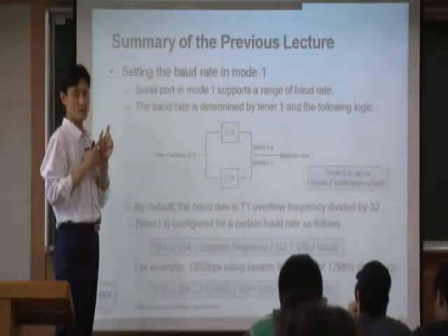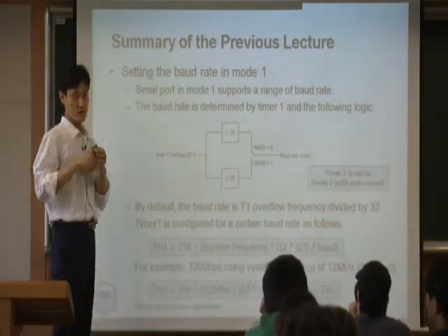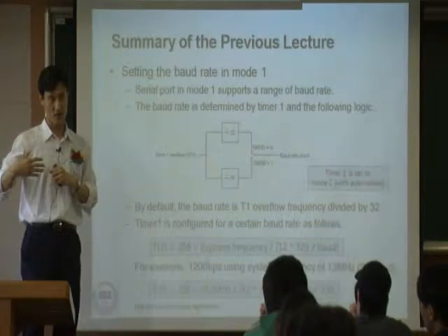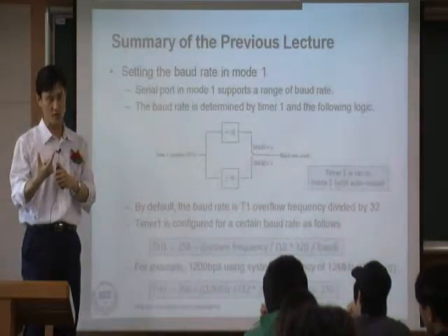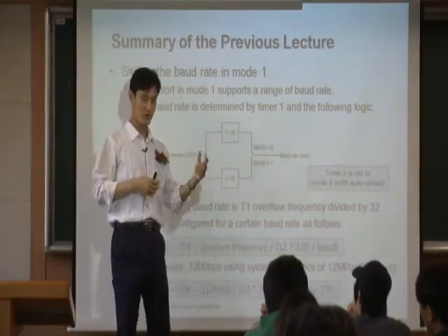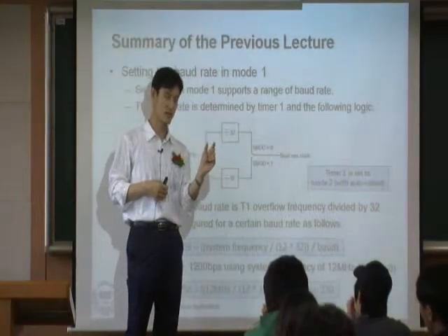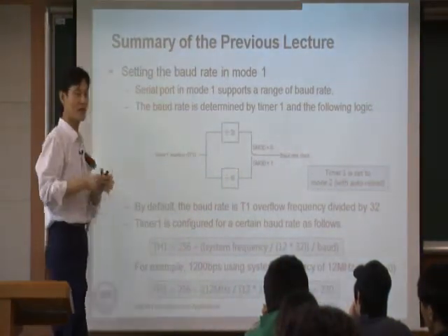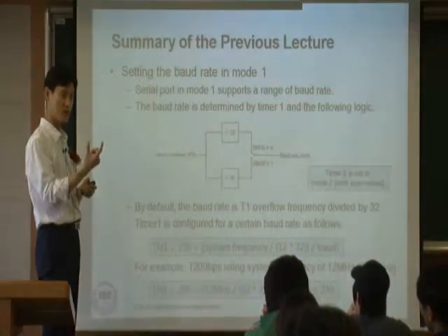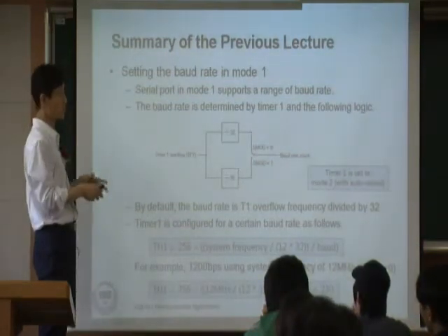microseconds? That's why we need a timer. The transmitter is running the timer to measure the 800 microseconds. The receiver also needs to run the timer in order to measure the 800 microseconds. That's the only way I can know the 800 microsecond bit duration. That's why we need a timer.